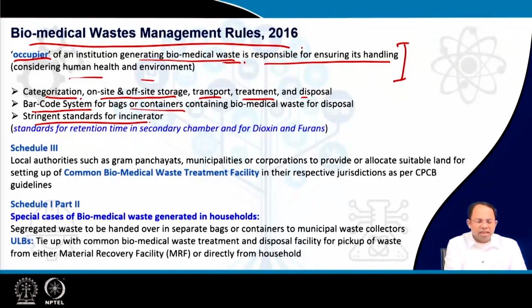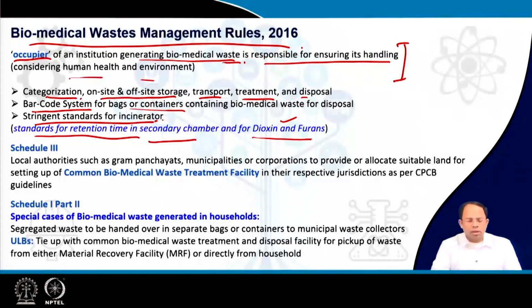Now, for the incinerators that are also proposed, a lot of stringent standards have been developed for the incineration process as well as the incinerators that are used to handle this biomedical waste. Because these are special kinds of waste, they need to be treated in separate ways. So, there are standards for retention time, particularly in the secondary chamber of incinerators. We have learnt earlier about the incineration process. In the secondary chamber, the retention time is controlled so that dioxins and furans are not produced. This is one big toxic element which has to be reduced. These are some of the aspects that have to be looked into.